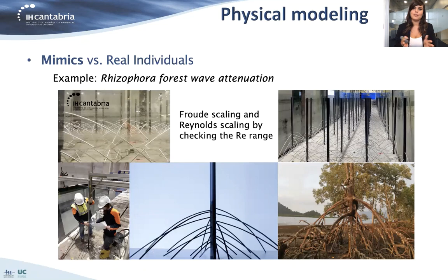As an example of experiments performed considering mimics, here is the representation of a mature Rhizophora forest at 1/6 scale, considering Froude similarity to scale the hydrodynamic conditions, and also Reynolds number similarity was considered by ensuring a sufficiently high Reynolds number in the model to ensure similarity in the wake structure between the model and the real conditions. A forest 26 meters long was built to analyze wave damping, and forces were measured in 9 mimics.